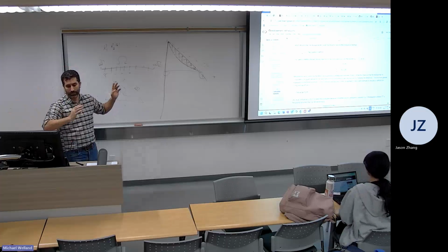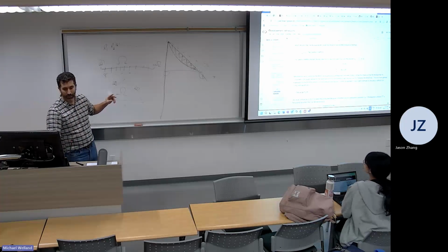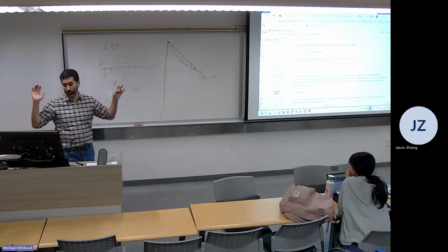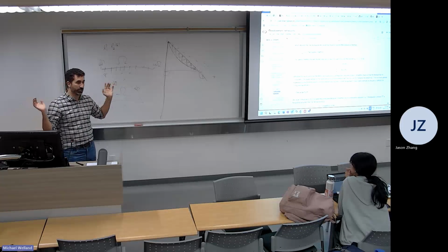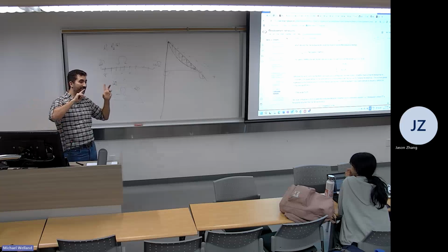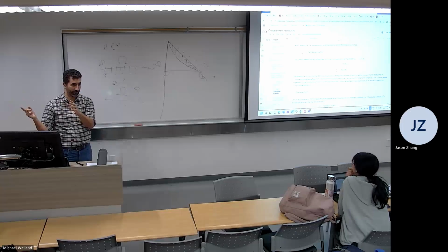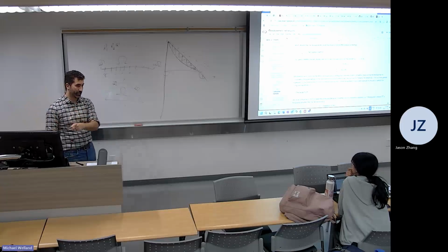So you get something that looks like the integral of your residual times your shape functions, where the residual depends on u, and u is defined in terms of those shape functions. This is what the equation is actually saying.